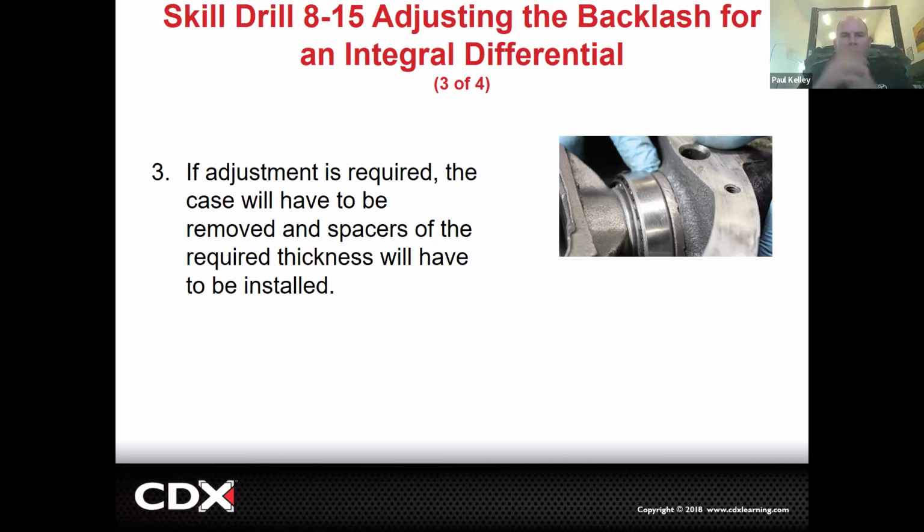Remember that? So the ASE had a question several times about you go up to this differential and you can't pull the diff out, you can't pull the center section and ring gear out, you've got to pry it out. Tech A says somebody banged on it with a hammer. Tech B says it's welded. Like, no, that's normal. If you unbolt those caps and it falls out, that thing had zero preload for sure.